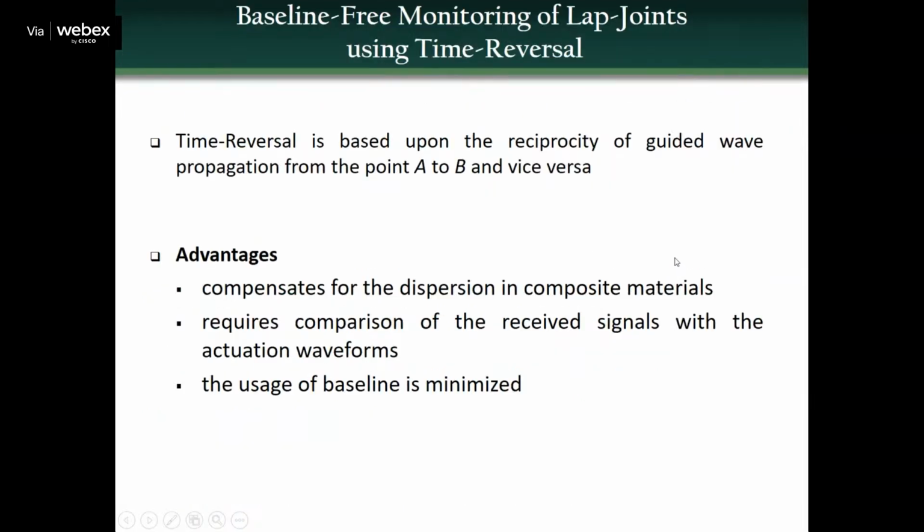Now we can try to understand the baseline free monitoring for lap joints using time reversal. So what is time reversal? We will see time reversal in ultrasonics here. Of course, for the lab session today, we'll look at the time reversal techniques for microwave. So in other words, time reversal is not limited to one form of physical waves. It can work for both mechanical and electromagnetic waves.